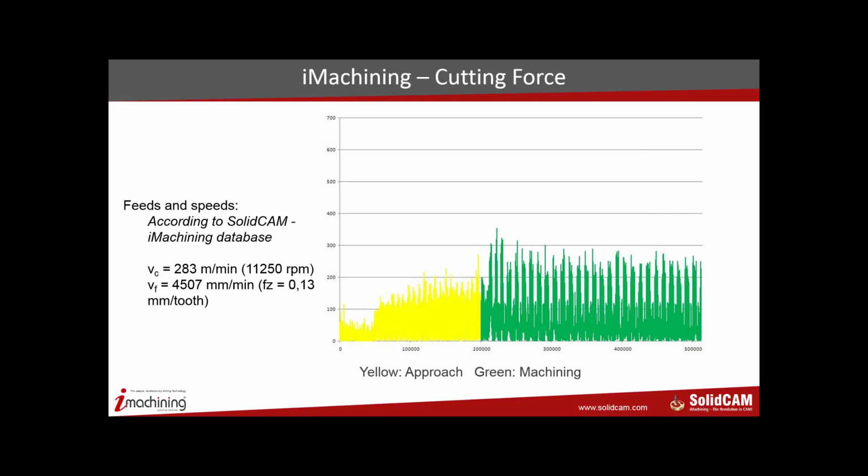So this should give your prospects who are worrying about the kind of load that's acting on the spindle, saying my spindle will be destroyed, a calming effect. You can tell them, look, this has been measured. We are not talking something out of thin air. This has been measured, that we generate much lower forces when compared to conventional cutting strategy. You can share this with your prospects.